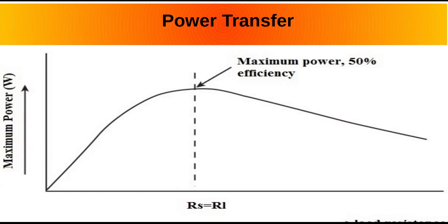That's why the modern ones also have temperature regulators, and they start shutting power down as temperature goes up. Because in semiconductors, which we'll talk about next week, you have the problem of thermal runaway. As silicon gets hot, its resistance goes down. So you have to compensate for that in a transistor amplifier.